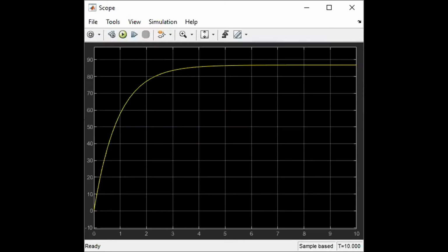See, this is the output which I got in my mathematical modeling. You can see the simulated output graph. This is what we discussed in my mathematical modeling. It started from zero and keeps on increasing the speed, like your fan. After a certain period of time, it attains the steady state RPM. So far we have not added any load to my DC motor, so it is rotating freely. When I add a load to it, the waveform will change.